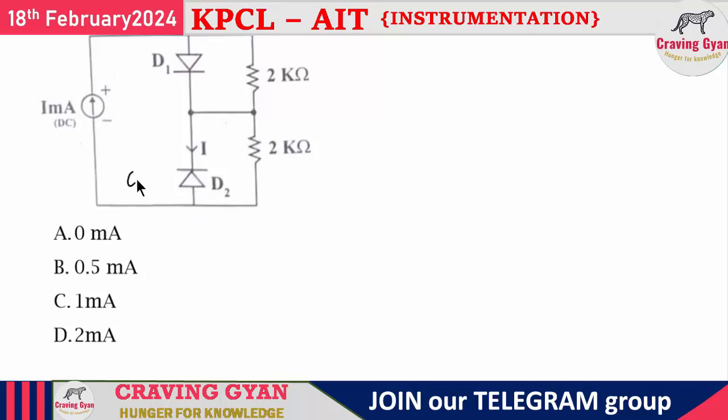So I can tell D2 as of now is in the off state, D1 is in the on state. Now I have to prove that the current flowing through D1 is greater than 0. I will assume that D1 is an ideal one, so greater than 0 volts is more than enough to conduct. Now the entire current will be flowing through D1; hardly a few milli or microamperes will be flowing through 2 kilo ohms, which is neglected.